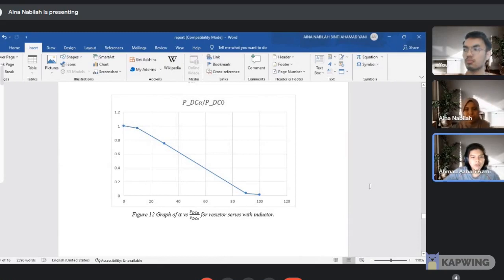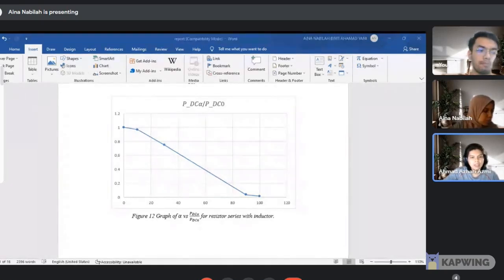From the output voltage waveform, we observe that there is a different waveform due to the presence of inductance load. With an increase in the delay angle, the voltage and the power ratios decrease because the current flow is delayed. The greater the turn-on delay, the more the current lags, as it is an inductive load compared to a purely resistive load.